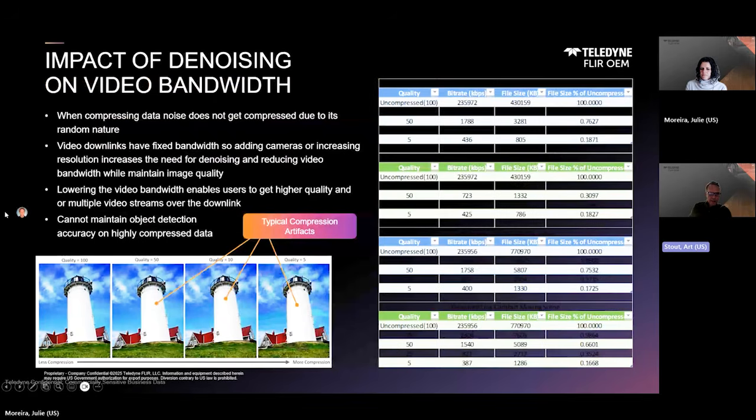And the real advantage then in the compression, beyond just image quality, is the reduction of bit rate. For many systems, there's always an RF link. So a lot of drone payloads and a lot of applications will transmit the video through an RF channel that typically has a very limited amount of bit rate, and you can basically set quality rates based on the bit rate available. So this gives you the opportunity to transmit the highest image quality at the lowest bit rate.